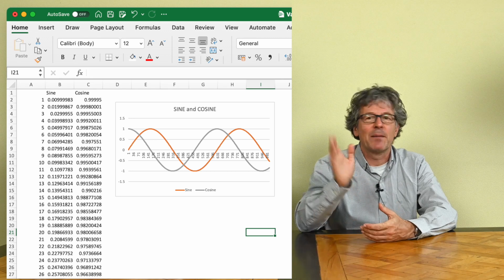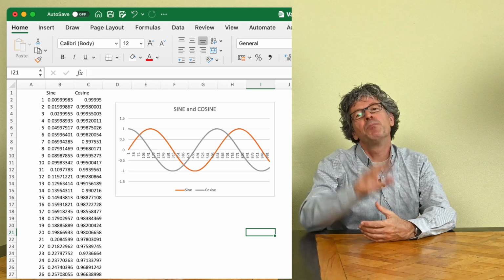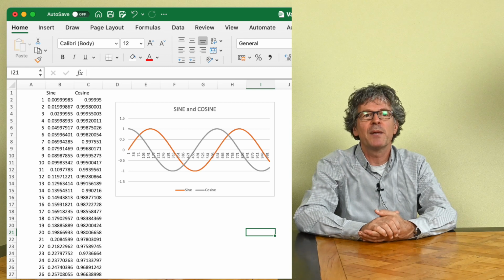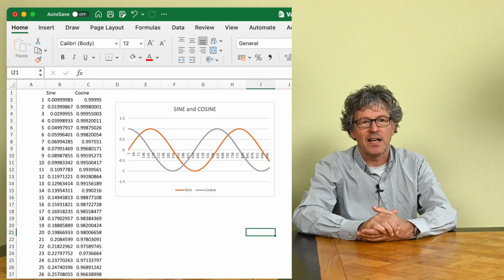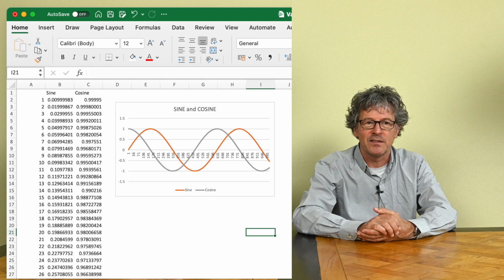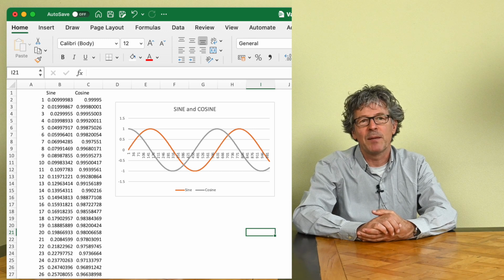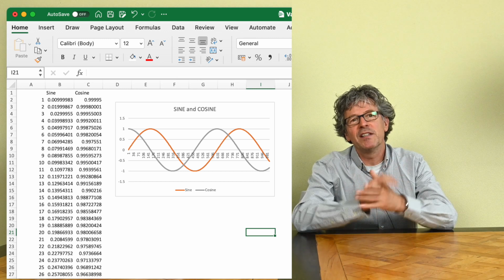And even if you wish to with Microsoft Excel, and I also did that, just simply creating certain IQ waveforms, creating them with 10,000 value points, putting exactly the markers the way that you want to make them. You export them as ASCII comma separated values. You input them in this IQ producer program. Then you might choose anything additional that you might want to have there as filters, or set the sample rate, and then it goes to the device. And all of these three modes actually work really well.